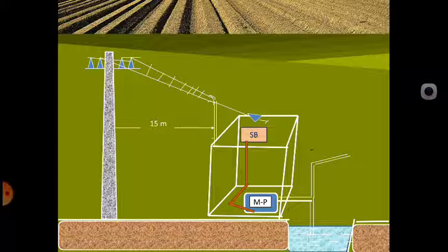Here, on the roof of the shed, we are going to place one stay wire to pull it, using the GI wire, to avoid very loose sag.